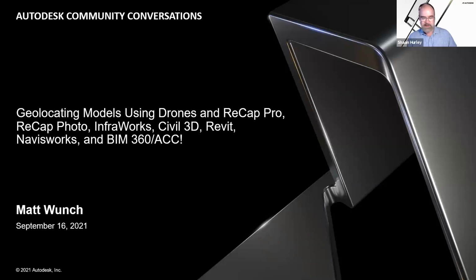And jumping over to InfraWorks, right? So we want to take that information and pull it into an InfraWorks model. So what we can do is fire up Model Builder, and it's basically a Bing Maps sort of interface. We can see the road type map, and then we can also look at it in a satellite image type of view, but very similar to navigating any other map. Left mouse button, pan around, the middle wheel will zoom in or out. We can specify an exact location if you happen to know it. In this case, I absolutely do know it, and there's that middle school that we were just looking at.